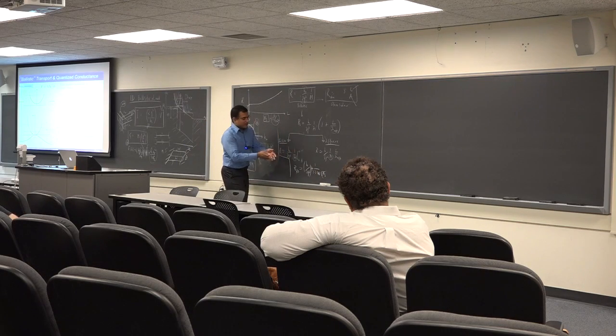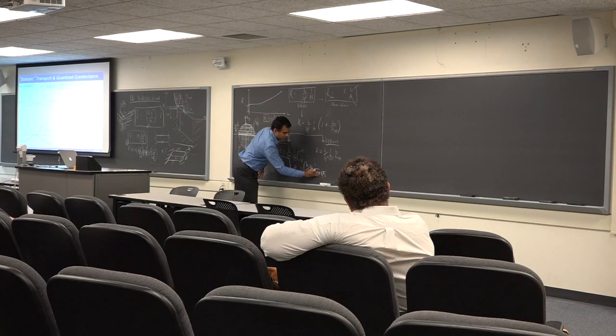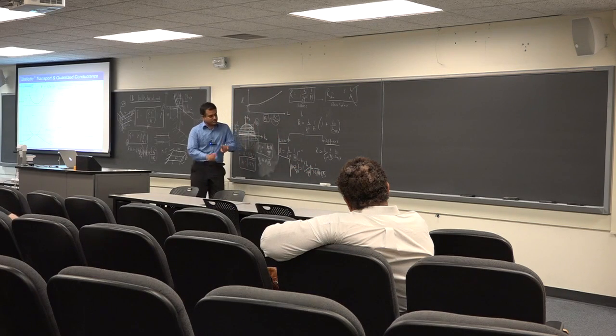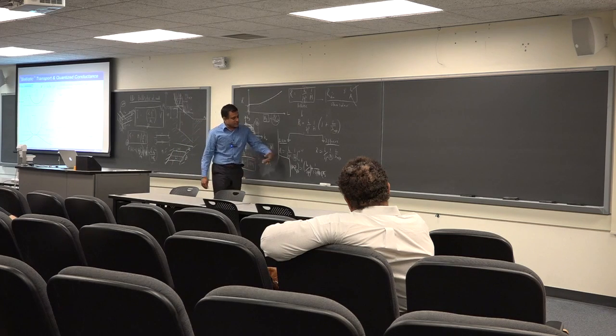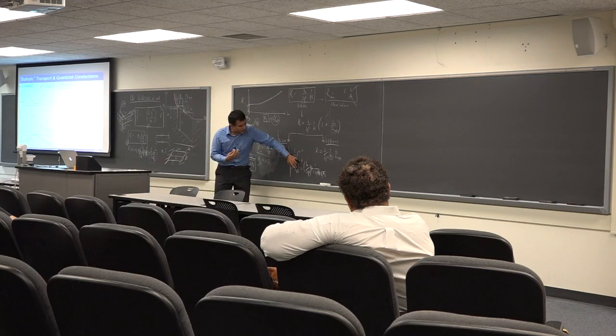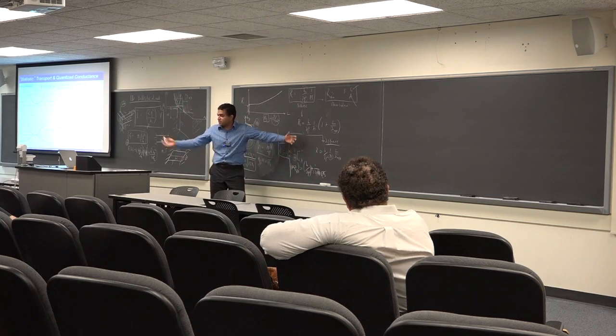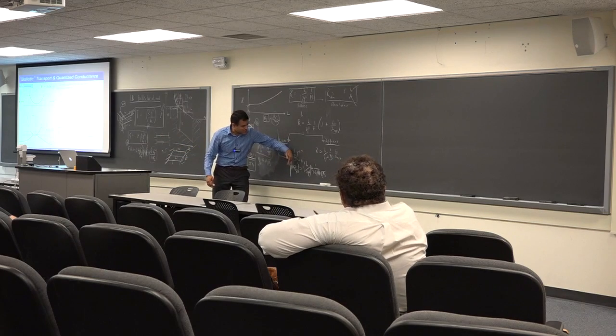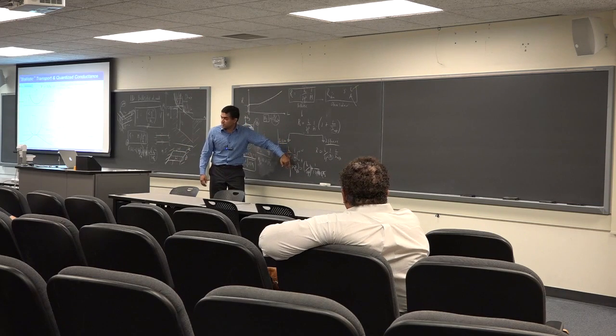And you can actually take the width to make it completely physical and take it here, w times the resistance of a 2D conductor. And you see that the stuff here has units of ohm times micron, or it's called the contact resistance. It's basically this contact resistance. Ohm micron, or milliohm millimeter, depending on how it's resistance times length. It has units of resistance times length.